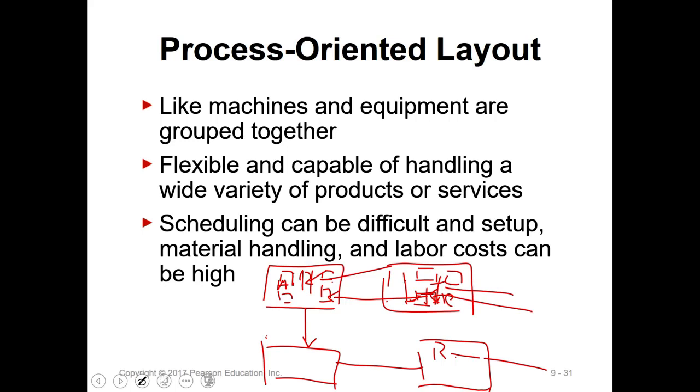The advantage of this layout is you can do a maximum variety of products because all of the machines are general equipment. But the disadvantage is low utilization rate of the machines. That's a high idling.